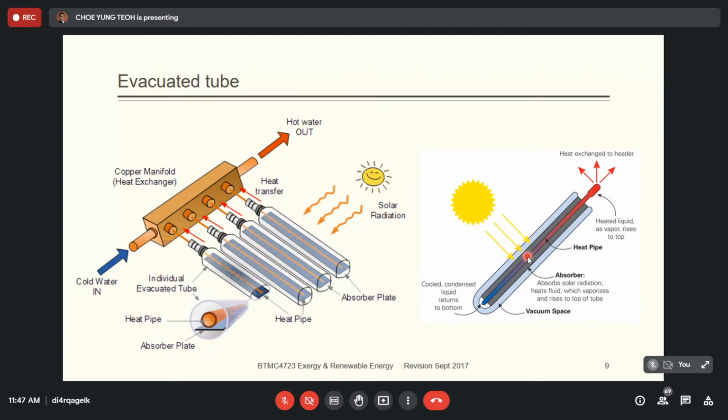So what happens to the gas? The gas has a much lighter weight, or much lower density, so immediately the gas will move to the top. On the top here, you can add a heat exchanger at this point to capture the heat. Maybe you have cold water pass through this heat exchanger. When the cold water touches the gas, it will condense back to liquid alcohol. Once condensed, it has a higher density, so it will go down.